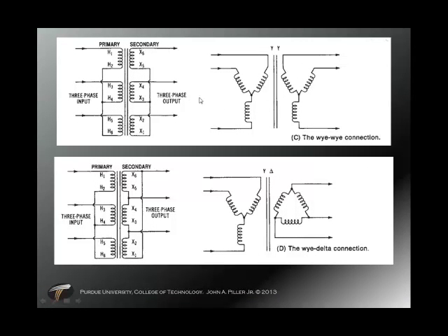Next we have a YY, okay? We already discussed how the Y would set up, but you have an input A, B, and C, and then between here on your low legs will be your neutral. A, B, and C, and here again is your neutral. There's your neutral point, there's your neutral point. I will use a caveat to say that a YY is not a desirable connection, and we're going to talk about that in a second.